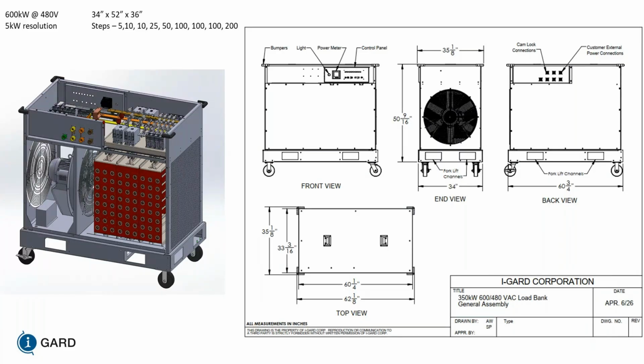You can certainly use a SCADA system to do that, and you can monitor fuel capacity, fuel discharge, and exhaust temperature of your generator. You can also measure exhaust temperature of the load bank and load profiling. As long as you have all the sensors available, you can monitor everything you want.